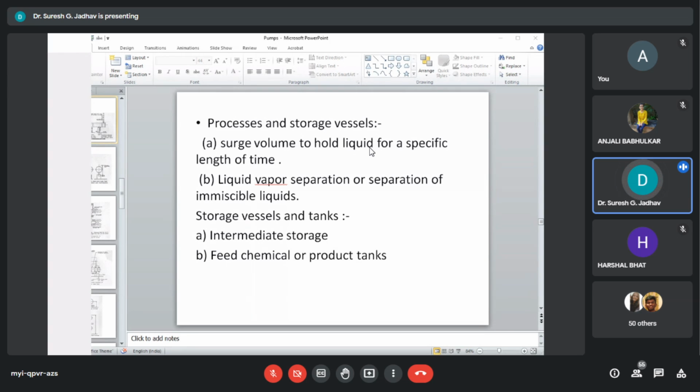The area required around a reactor is much more compared to other process vessels. The manual loading of these, if required, will be facilitated. Hence, this reactor will be located passing through the operating floors with the manholes located at accessible levels. Space for utility manholes and process inlet manholes, if required, shall be provided for in the layout.